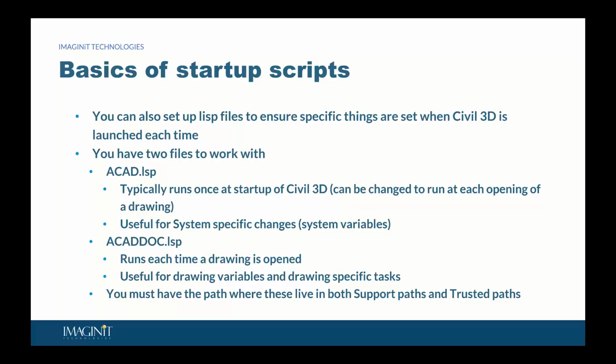So every time I launch ACAD, it's loading certain things and changing certain variables. For me, it's changing my OSNAP variable. I like my OSNAP to be turned on, and my preferred settings. And then the ACAD doc does something different, where I'm now focused on drawing-specific things.